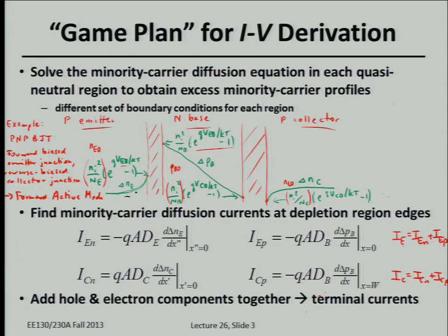And which direction is it flowing? I mean, the real current. It's actually going to the right, because you have electrons diffusing to the left, so that contributes positive current going to the right. But the gradient is negative? Well, sorry, the gradient is positive. Yeah, the gradient is positive. In any case, it's contributing current flowing to the right, as we know under forward bias.